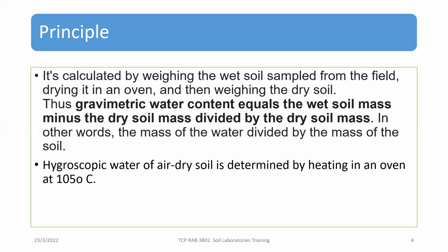In the liquid phase, there are 2 types of water. The free one, within the pores, between the pores, there will be water, and also around the soil particle. Around the soil particle, it makes a thin wall, and this type of water is called hygroscopic water. And this hygroscopic water cannot be removed unless the soil is dried at a temperature of 105 degrees centigrade.